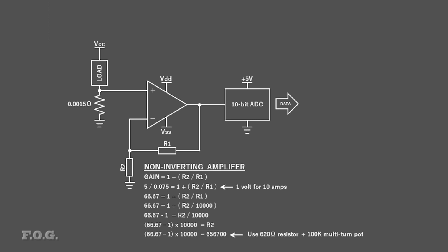And with that gain tuned, we can now be confident that the full scale ADC count of 1023 will match to that of the 50 amps maximum of the shunt. So in the end, the formula that we would use to calculate the current would look just like this. And for example, if the ADC returned a value of say 268, the calculation returns a current of 13.1 amps.